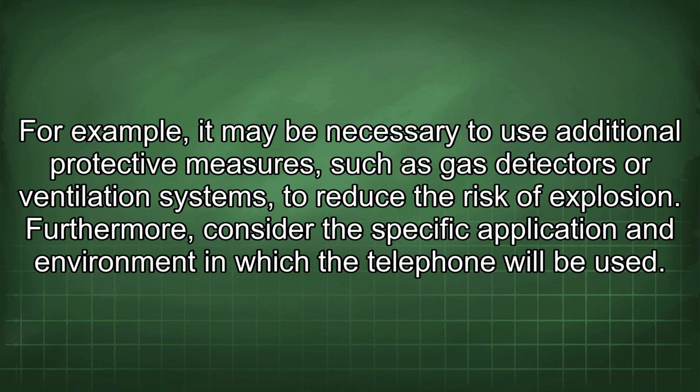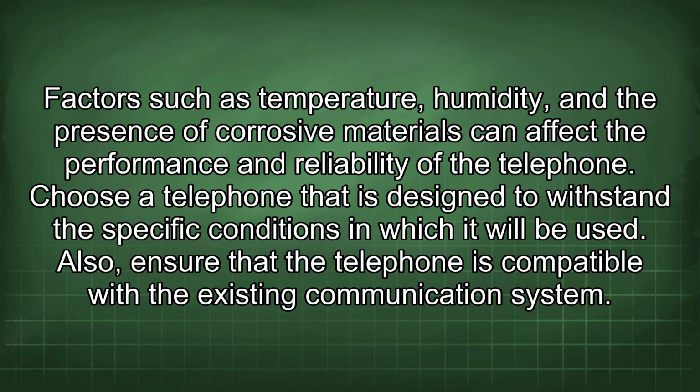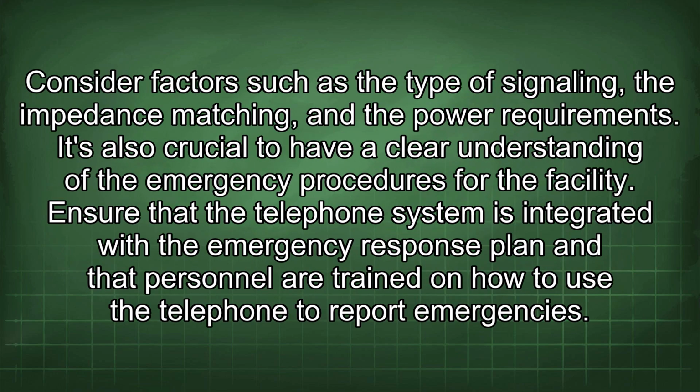Furthermore, consider the specific application and environment in which the telephone will be used. Factors such as temperature, humidity, and the presence of corrosive materials can affect the performance and reliability of the telephone. Choose a telephone that is designed to withstand the specific conditions in which it will be used. Also, ensure that the telephone is compatible with the existing communication system. Consider factors such as the type of signaling, the impedance matching, and the power requirements.